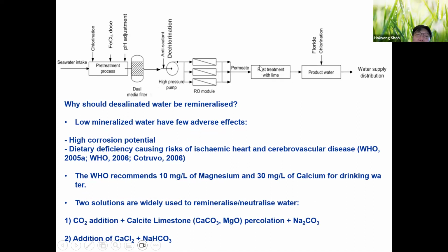Post-treatment: why should desalinated water be remineralized? Low mineralized water has a few adverse effects. One is high corrosion potential. If you don't have minerals, your pipeline, let's say stainless, will be easily damaged, so the corrosion potential is much higher.